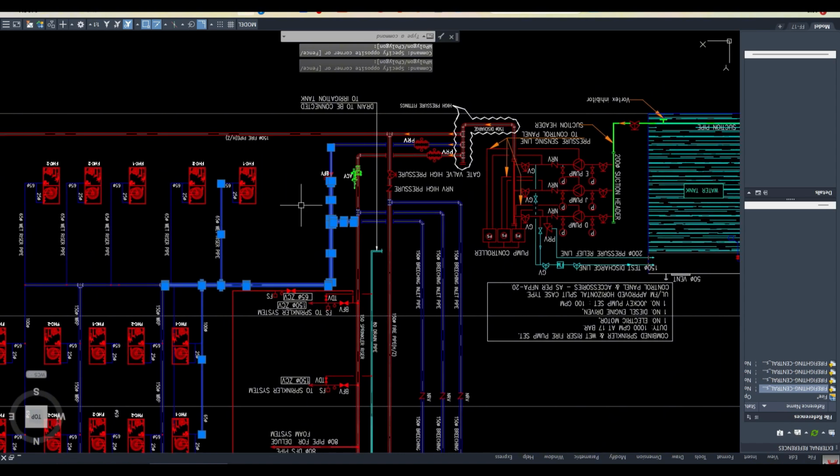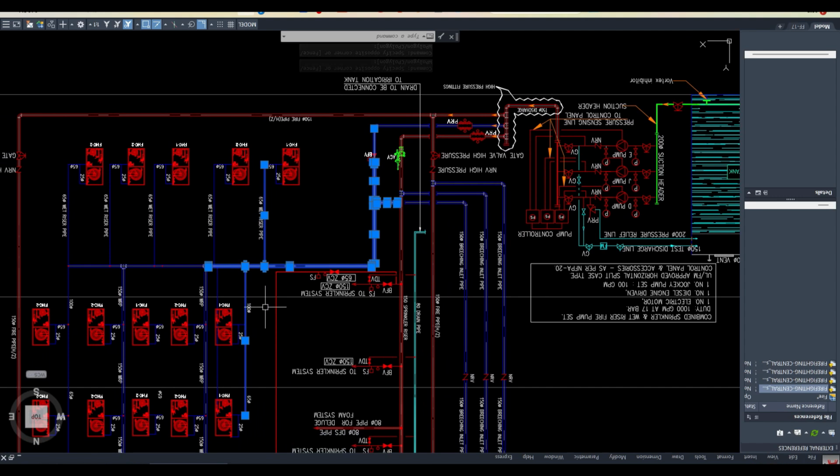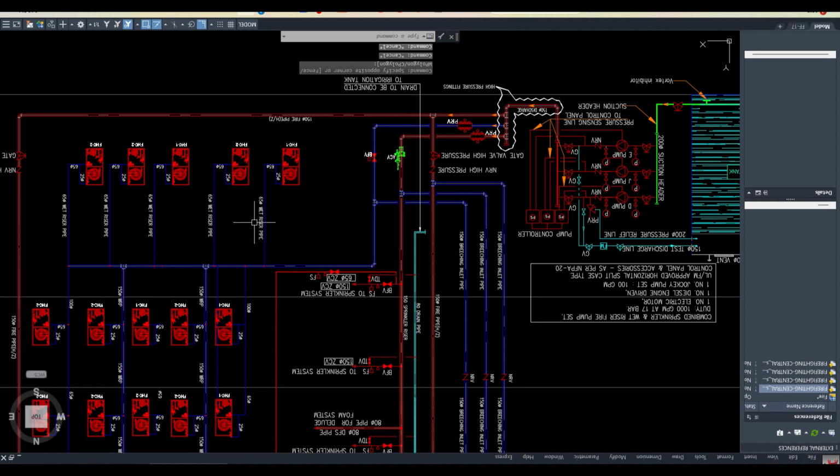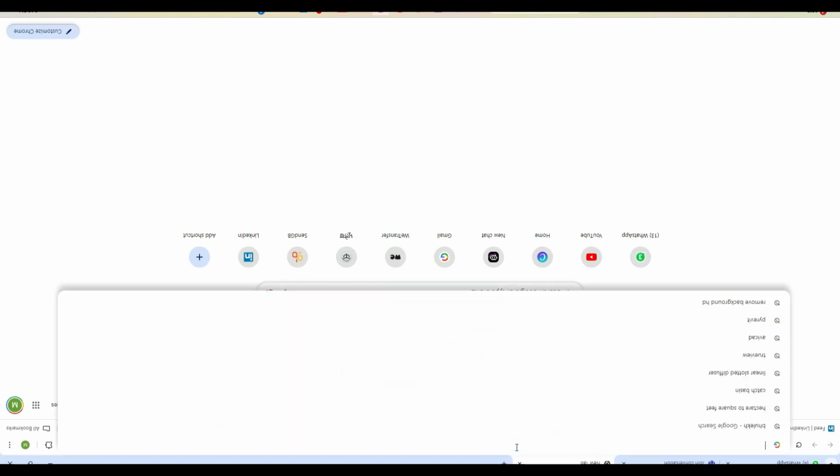In that case, class 1 will consist of landing valve. Now what is a landing valve? A landing valve is a valve where you can connect the pipe, and it is normally situated near the staircases, because that is the most accessible location in case of fire for the firefighters to come and get the water to suppress the fire. That system we call the landing valve system. One valve will be there, I'll show you in the picture.